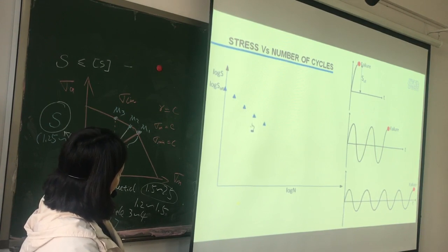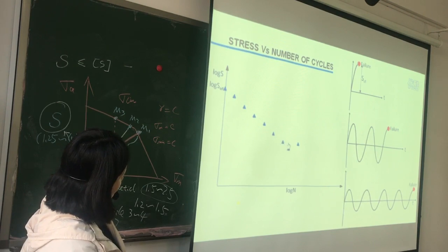But not forever. You can see after a particular stress amplitude, even with a slight decrease in stress, the number of cycles required to make it fail increases drastically. Or in short, if you have stress amplitude below this limit, the number of cycles to make it fail jumps to infinity, or the material never fails after this limit.